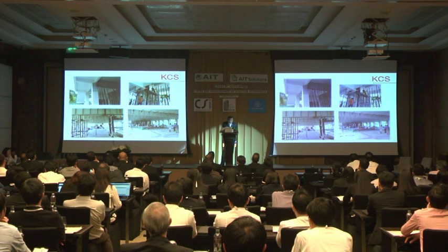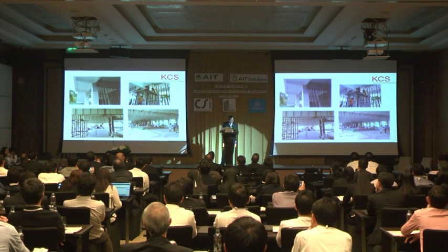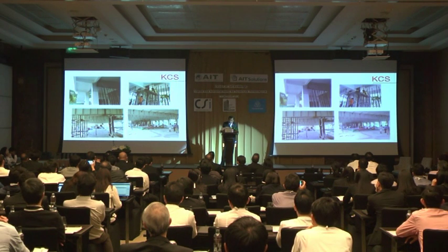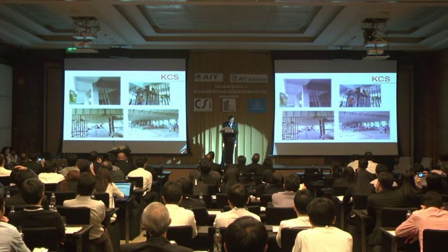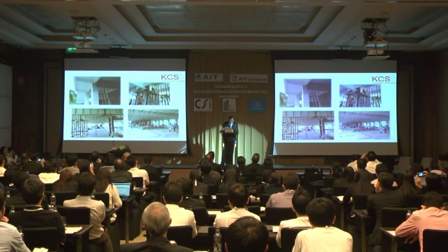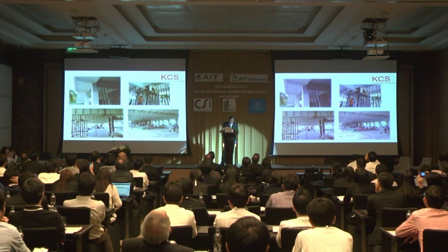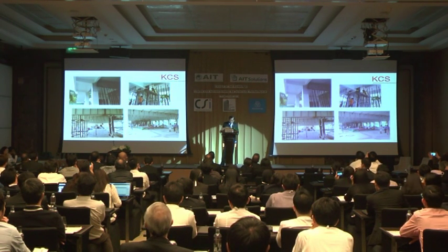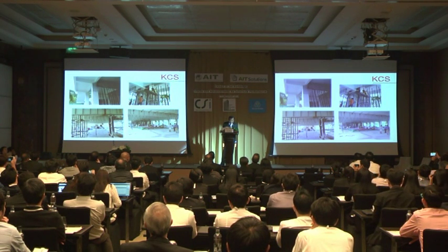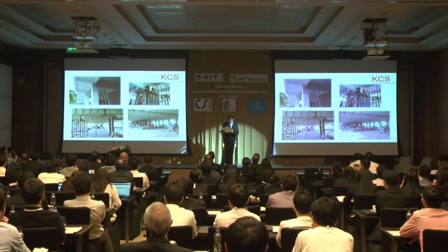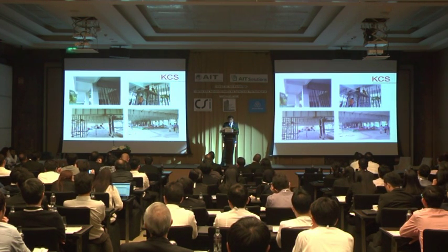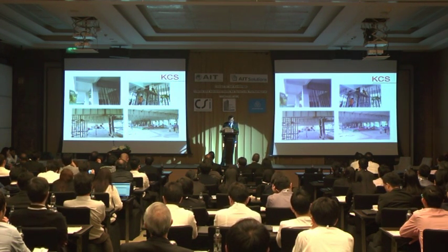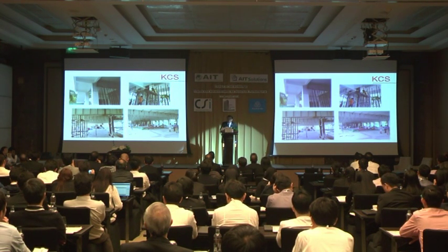The transfer of the existing building weight to the newly installed transfer beams is crucial and normally gets ignored by inexperienced engineers. Therefore, it was required to jack up the existing central column load before cutting the column, and then release the load back to the newly installed beam to ensure full transfer of the existing weight to the new structure.